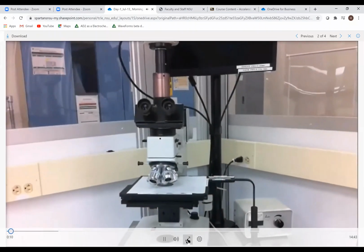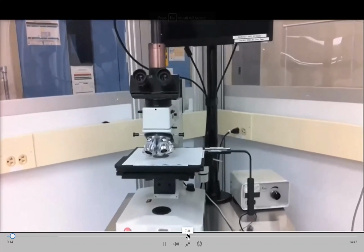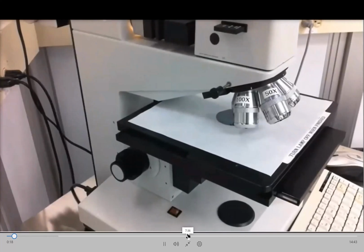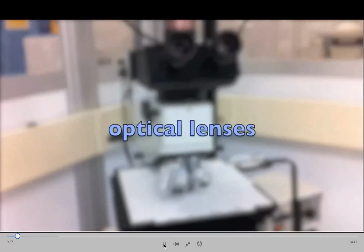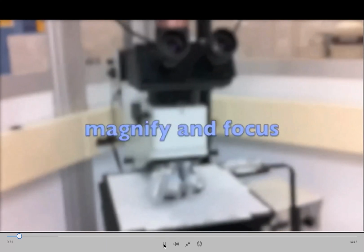Introduction to optical microscopy and the Leica Ergolux reflective microscope. Optical microscopy is a measurement technique which uses the reflection of visible light off of the surface or some plane of a sample and a series of optical lenses, which allows us to magnify and focus an image of the sample being investigated. It's a non-contact and non-destructive technique.